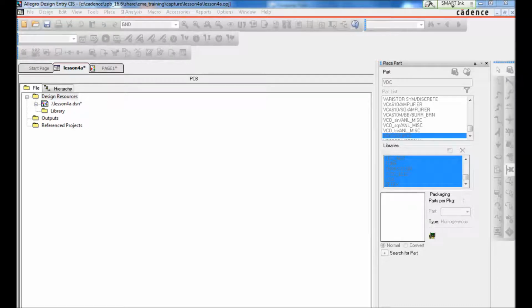Eddie here. We're going to start off lesson 4-2, creating a schematic page. So the lab objectives here are viewing a reference schematic, add a header connector, mirror the connector, add and copy decoupling capacitors, add wires, add net aliases, add no connect and power ground symbols, add bus entries and wires, add off page connectors, and view the design cache.